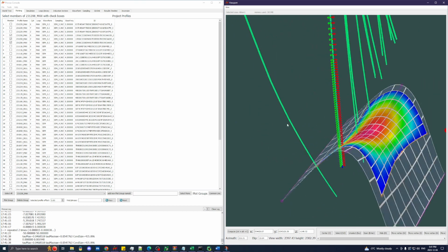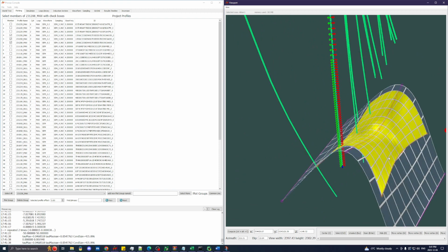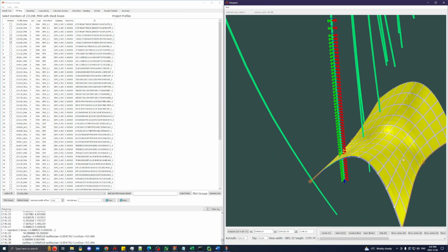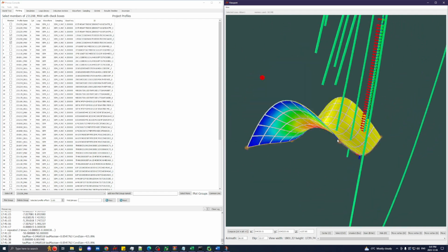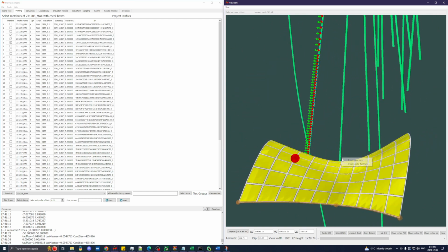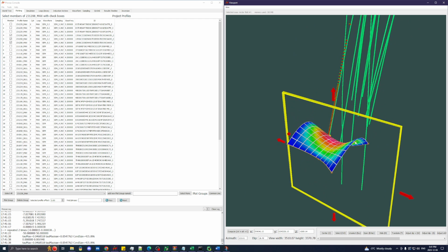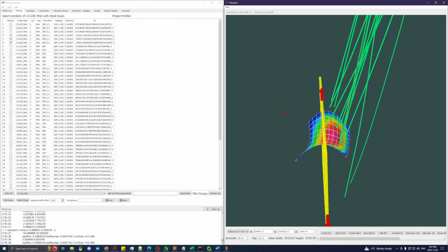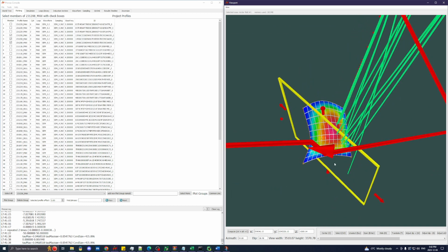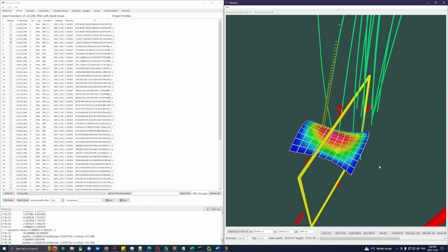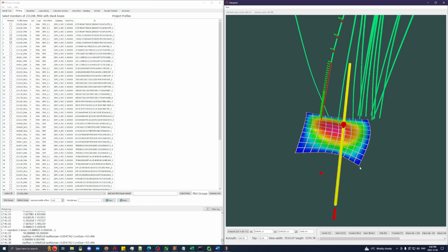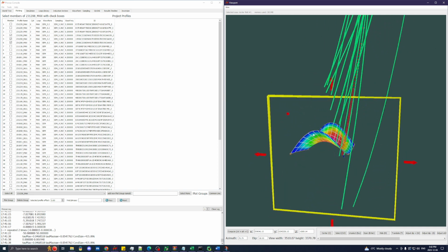And so finally, to end this video, I'm just going to show you how you would go about creating a vector field. In our viewport, if we hold control and right click, it'll bring up this option again. This time we're going to click create vector field. You can see this made this rectangular frame here. I selected it with control left click. Now I'm going to make it so that it's intersecting our conductor, and I'm pressing D here just to manipulate it, and then I'm holding T and right click dragging to center it here.